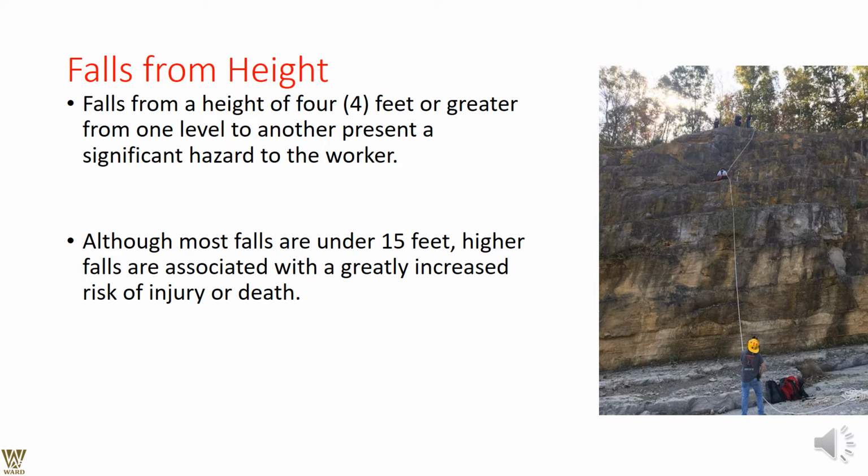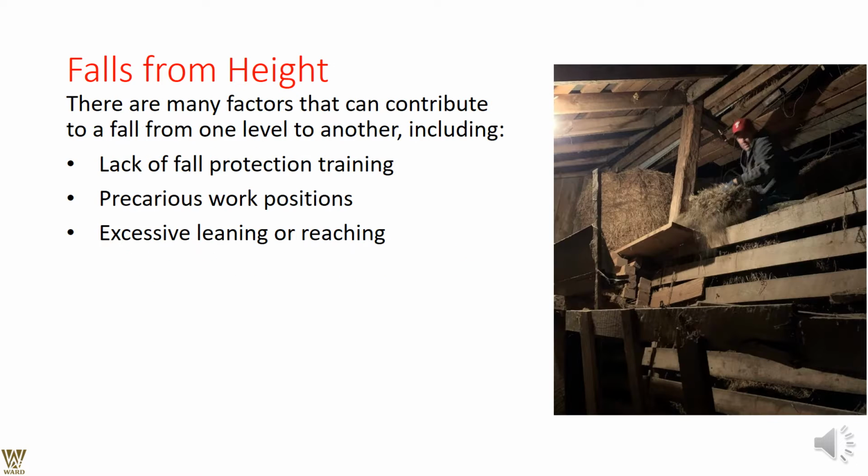Now, fall from a height. Look at what is happening, look at the distance we are looking at. Here is the distance, just to point it out to you. A fall from a height of 4 feet or greater is a significant hazard for a worker, and from 15 feet, the risk is very grievous and it might actually cause death. That is what I'm trying to inform you. A fall from a difference of 4 feet might cause a definite hazard, but a fall beyond 15 feet is ultimately serious.